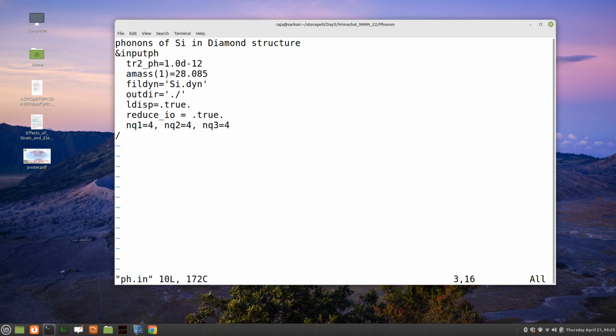Okay, here we are using 10 to the power minus 12, and generally for SCF we were using 10 to the power minus 8. The default value is 10 to the power minus 6. And for this, minus 12 is the default value. So I am putting the default value, but sometimes this may not be sufficient, and you have to go to minus 13 or minus 14 or even minus 15. So we can go up to there. That is the tradition and practice mostly.